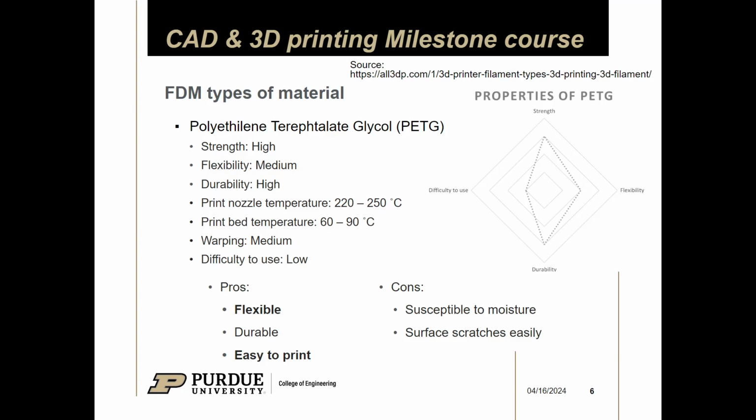Again, it's susceptible to moisture, so if you ever plan on printing it, make sure it's in a nice dry environment or get a dry box. But yeah, that's more technical stuff that is kind of more than you need to know. It's a pretty great material. It's a little bit stronger than PLA for most cases, so that's why I prefer it over PLA. But again, circumstances, desk toy, you don't really need it to withstand being run over by a car or something. So yeah.